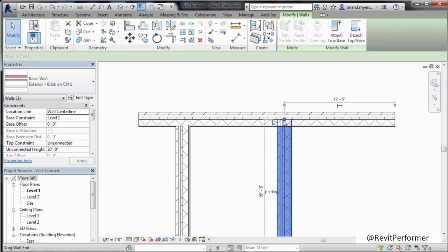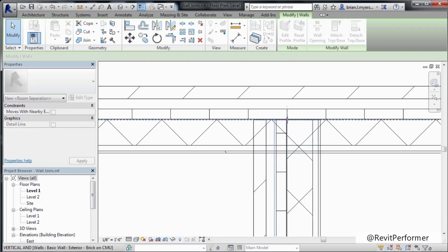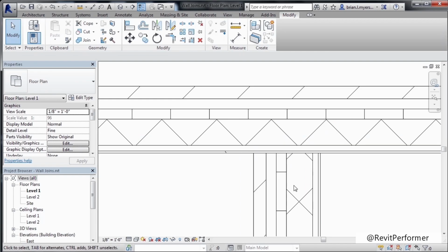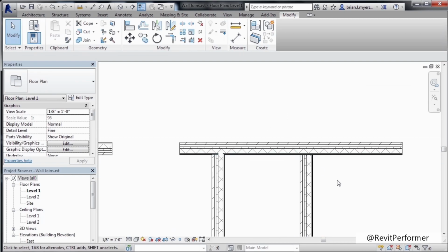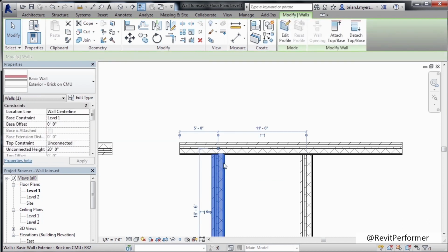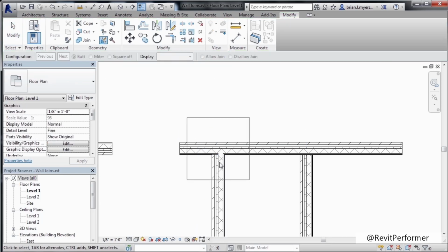We'll select there, zoom in, click on the little dot, pull it back until it's at the front face of this wall, and then click. And now we can have both of these walls touching each other without actually joining or cleaning up on one another. Now the next thing that we can do is basically the same steps over for the wall over here on the left-hand side. Select on the wall, come up here to the Wall Joins tool, select on the intersection of these two walls. Now let's leave this allow join the way that it is.